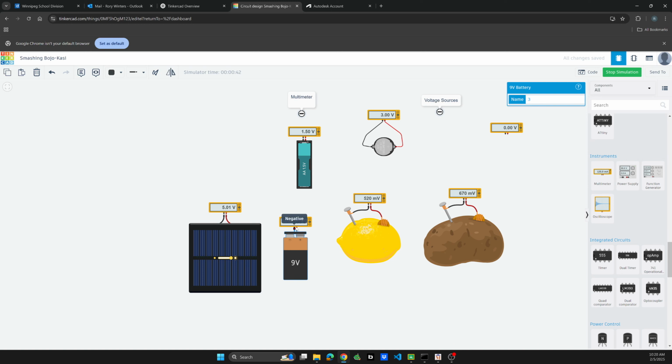With this, it's a 9-volt battery, so you expect it to have 9 volts. Now, in truth, it's varying degrees of charge state, right? There's a chemical inside a 9-volt battery and a AA battery, and it depends on what level it's been used up. So sometimes it'll be over 9 volts, like 9.5 volts, and sometimes it'll be considerably less than 9 volts. If you're using a 9-volt battery in a circuit, typically if you measure the voltage with a multimeter and it is less than 9 volts, you probably should start thinking about changing it out. And if it's at 7 volts, you should definitely change it out.